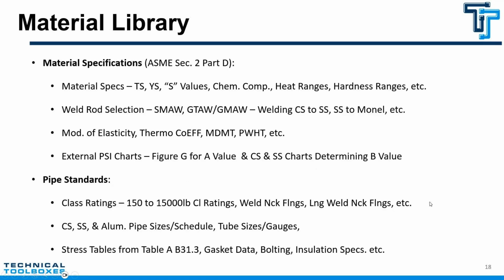Material specifications. Let's talk about that. The material specs: tensile stress, yield stress, stress values, chemical components, heat ranges, hardness testing. It has the weld rod selections. It has the modulus of elasticity, thermal coefficients, minimum desired metal temperatures, post-weld heat treatment evaluations.